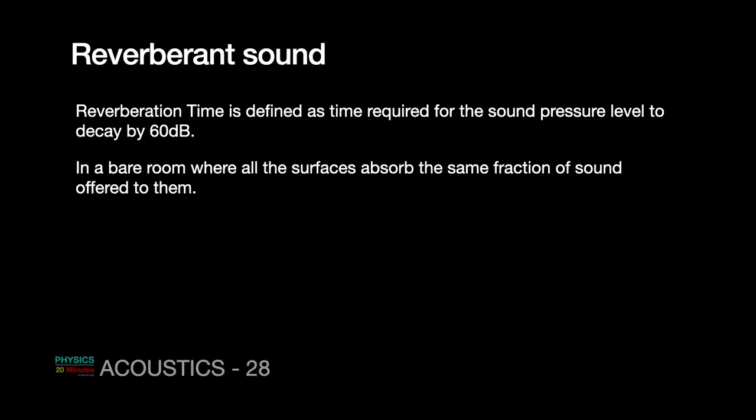So reverberant sound, as we have already discussed, reverberation time is defined as the time required for the sound pressure level to decay by 60 dB. In Audacity, we have done that experiment. If you remember, if the sound pressure level is say 0 there, we have found reverberation time is the time that it takes for the sound pressure level to drop by 60 dB. So that we have already done.